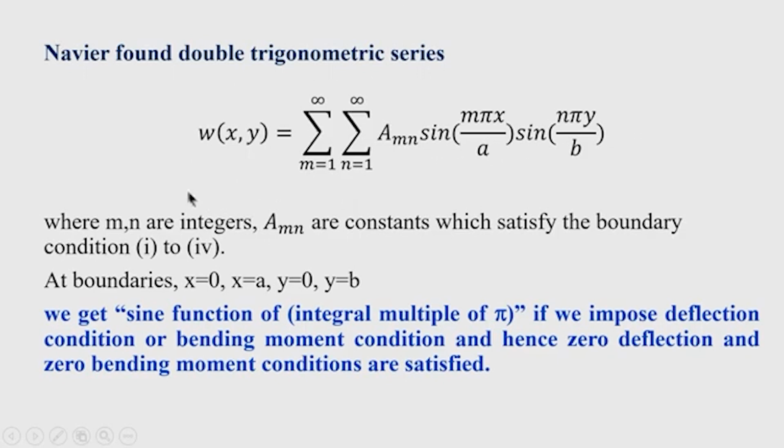It is a very well known series and it gives the value of deflection and other stress resultants, converging very rapidly. Of course, if you go to stress resultants with higher derivatives, the convergence may be slow, but within say a maximum of 5 to 7 terms, you will get convergence within the acceptable limit.